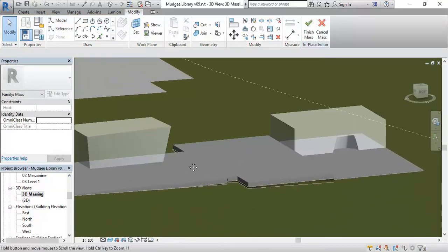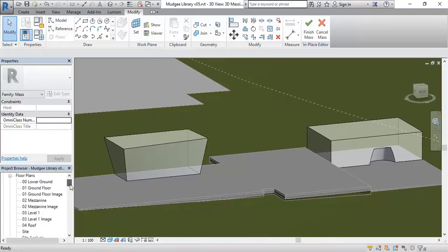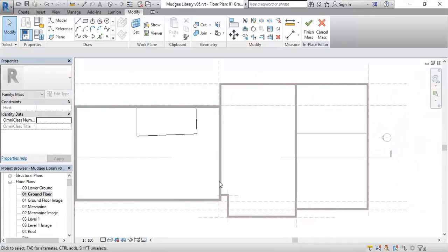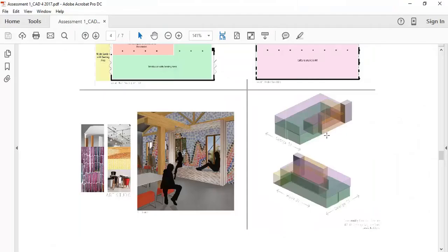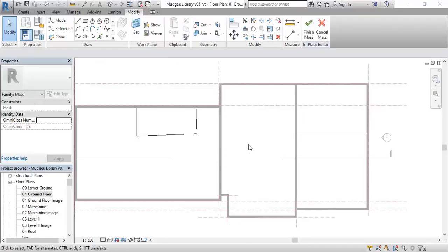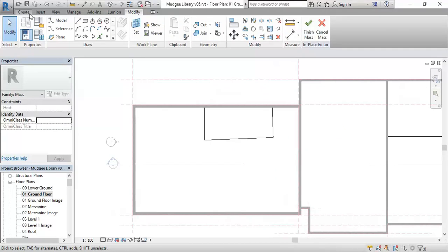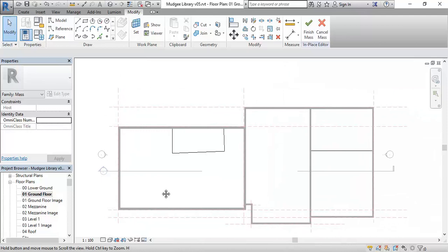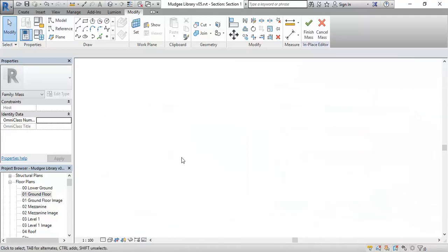So those are all extrusions though. Maybe just to show you a little bit more about the way this massing works. It probably isn't essential for the work you need to do here, because you can see if it's just block forms like this, you can make them all with extrusions. But you may want to do something a bit more involved. So a good example maybe is a revolve. So to do a revolve with a mass, I might go to the section view